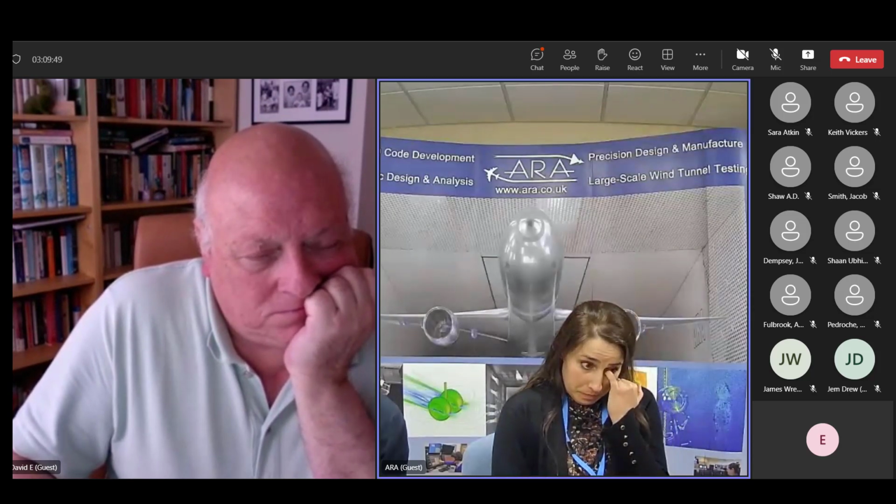Ultimately most of the thermal effects are localized within the balance. What we're looking for is temperature gradients across the beams, and this is what causes the strain. So what temperature the rest of the model is at is not necessarily going to affect those local variations in temperature.